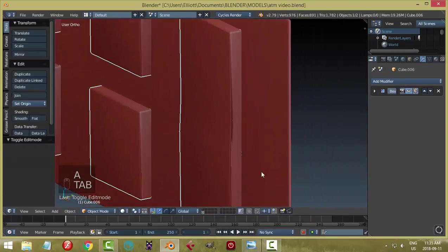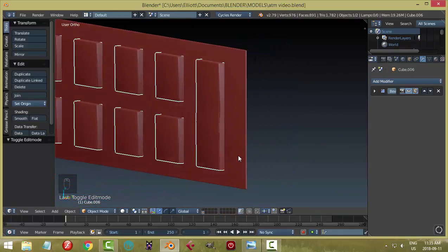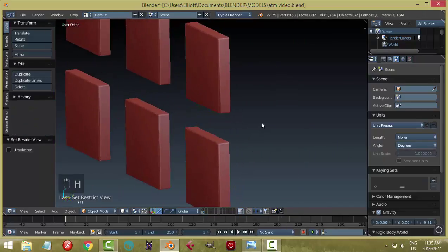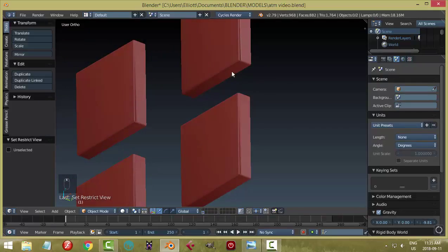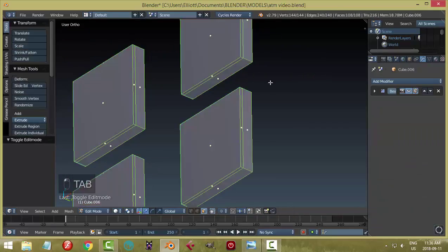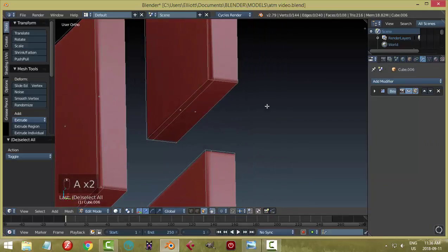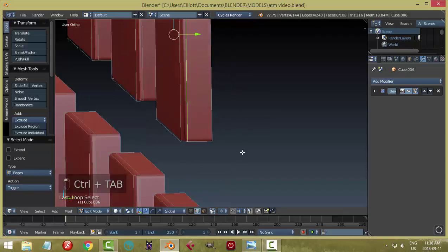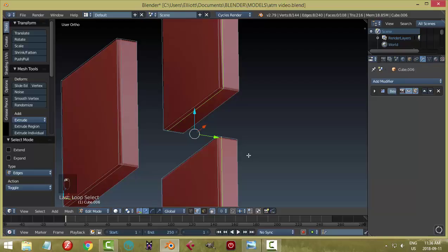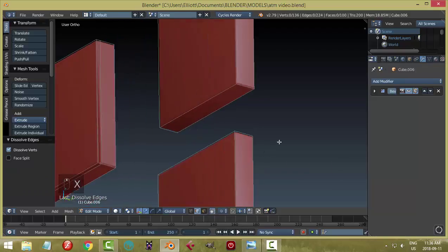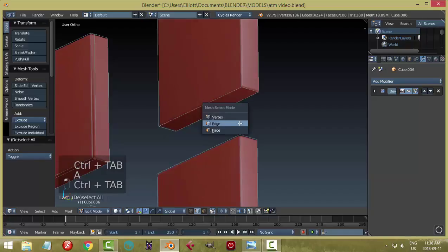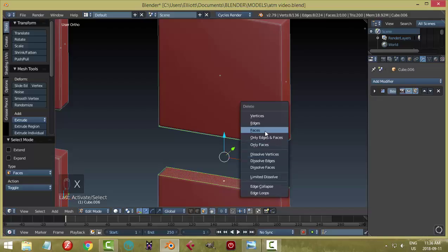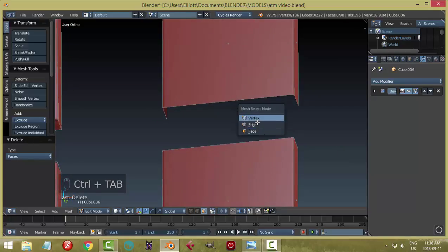Okay, let's have a look at that, and we'll see that we got some funny stuff going on. All right, let's undo that and see what's going on. Let's select that and hide it and see what I've done here. Because I added that edge loop, I have some other little pieces. I think, what have I done exactly? So here's what I could do. I could try getting rid of this edge loop here on both of those. X, I'm just going to go dissolve edges. And then let's try to, in face selection, get rid of that face. In this face, X, delete faces.